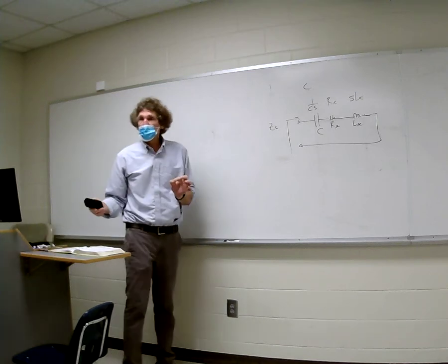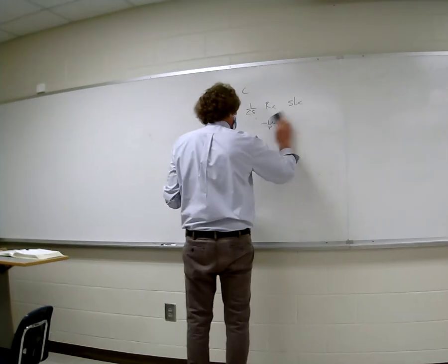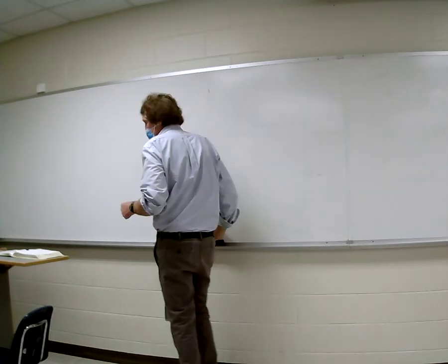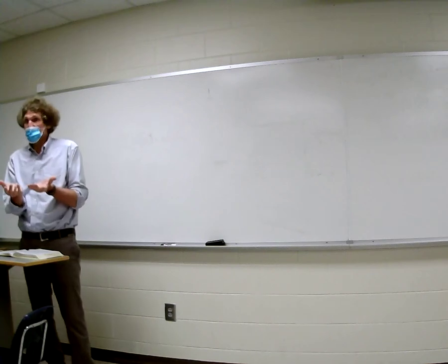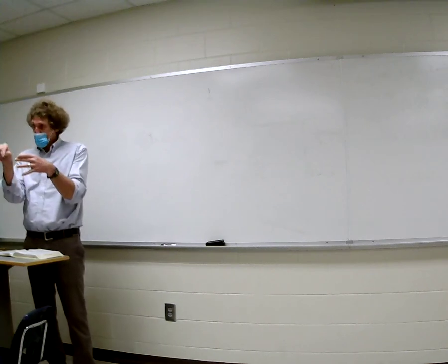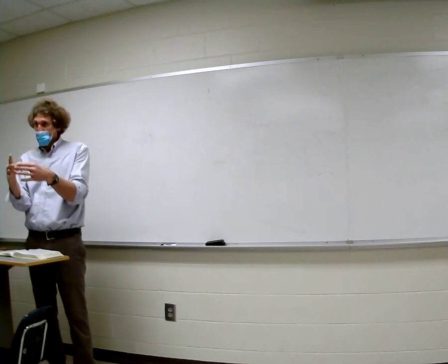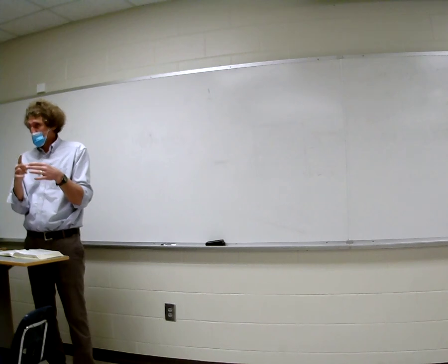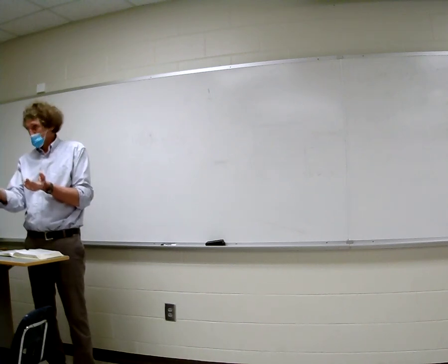That's a signal ground. And it's also a chassis ground. Now a chassis is just a metal box that contains a device. A signal ground can be on a single board. It has a ground point, just a breadboard. A chassis ground, if you had 20 boards on there, would be the metal enclosure held at 0 and everything measured with respect to that.